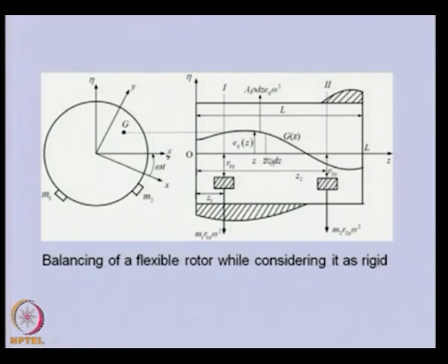In that particular case, if we rotate the rotor at any speed, and if deformation takes place, then also we can be assured that it will balance this particular unbalance in the rotor. But putting this kind of continuously varying correction mass is not feasible in practice. So, obviously we need to limit ourselves, and in that case we do balancing up to a certain speed.